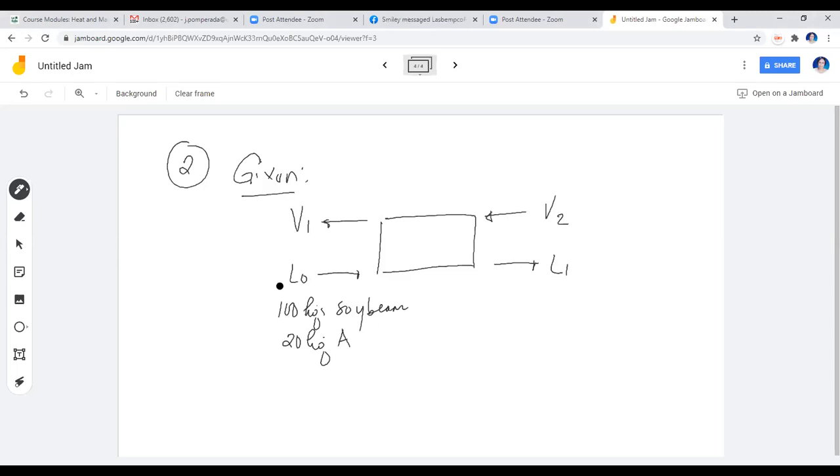And since this is 100 kilograms of soybeans and you have 20 kilograms of oil, 20% oil, then the rest of this 100 kilograms would be your B. So I'm writing now specifically the solute as A, which is our oil, and B, which is our inert insoluble solid present in our original soybeans. Now, in this case, we're using pure hexane with the value of 100 kilograms. Since this does not have any A, we'll have here XA equal to 0. Okay?